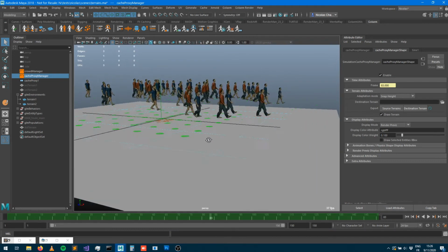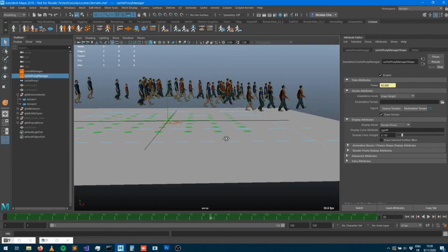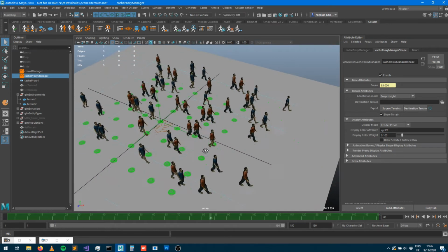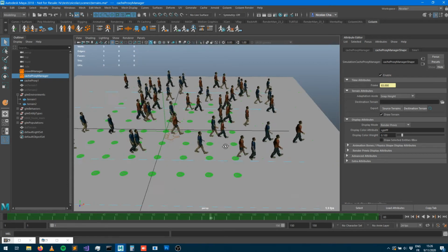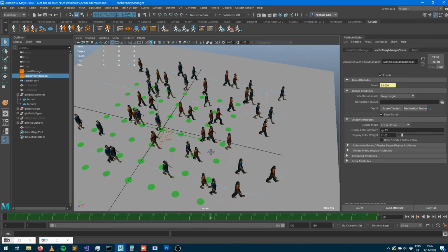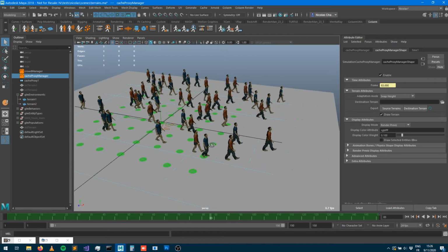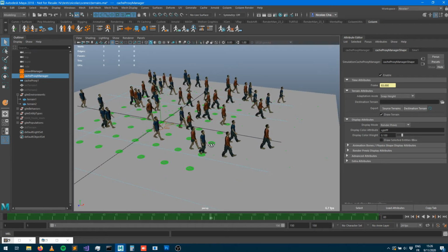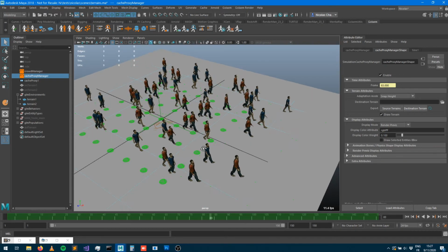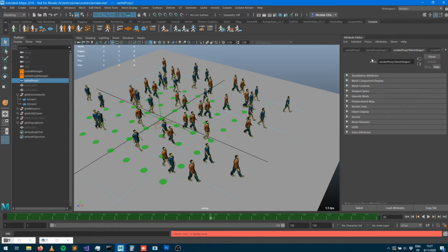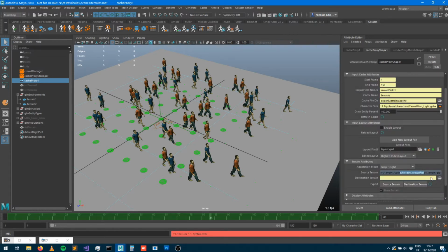And this is one of the issues here. The thing is, the terrain is kind of performance intensive. It takes some computation power to export some geometry. Here my geometry is pretty simple, but sometimes we end up with terrains which are really expensive, and we don't want to update and re-export the terrain geometry every single time we export a simulation cache. So the terrain is only exported if it doesn't exist. If that GTG file doesn't exist in the same directory as the simulation cache file, your terrain will not be exported even if it has changed, even if the geometry has changed, even if the terrain which is used has changed, it will not be re-exported anymore.